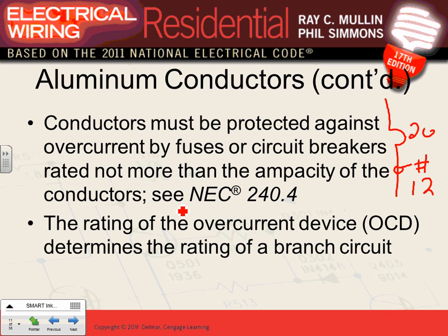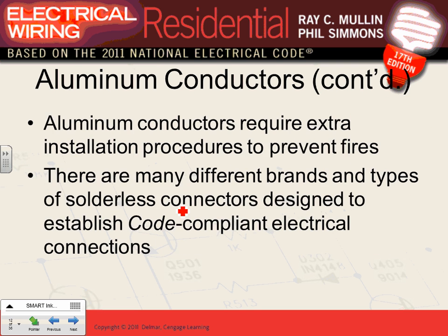Now, there's a few things we talked about yesterday, guys. We talked the small conductor rules. Remember the small conductor rules up to number 10? And we talked about when to use 60 and 75 and use the derating. Any comments, guys, about these? When we go commercial, we'll start talking about tapping conductor, the rules for tapping conductors, and it will be slightly different.